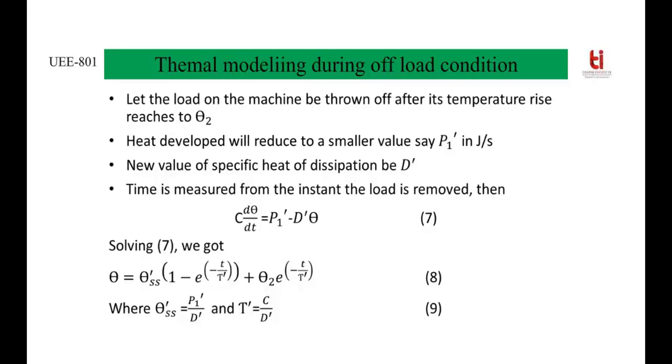Solving this first order differential equation, we can write theta is equal to theta ss dash times 1 minus e to the power minus t by tau dash, plus theta 2 e to the power minus t by tau dash. Theta ss dash is the new steady state temperature, and tau dash is the cooling time constant of the machine. Theta is the temperature of the machine at any instant t. Just like thermal modeling of the machine during loading condition, we can write theta ss dash is equal to P1 dash by d dash, and tau dash is equal to c by d dash.